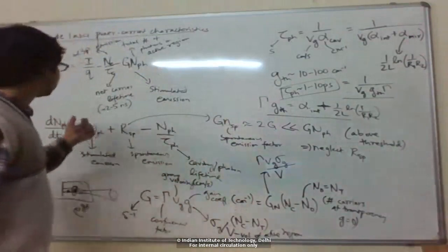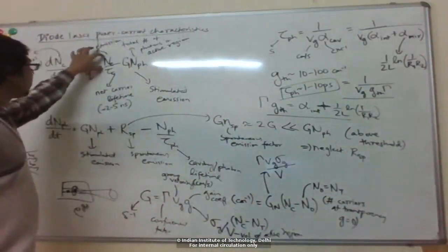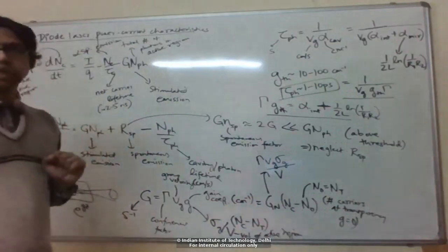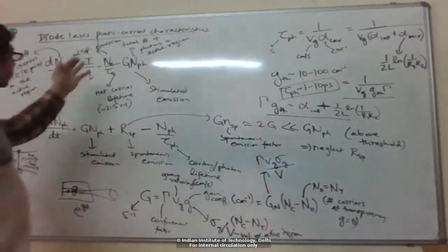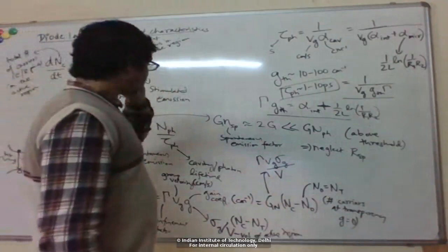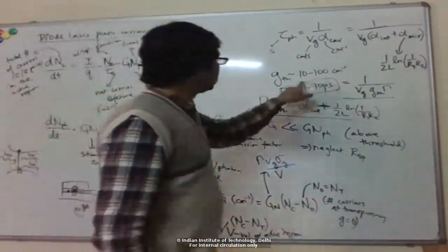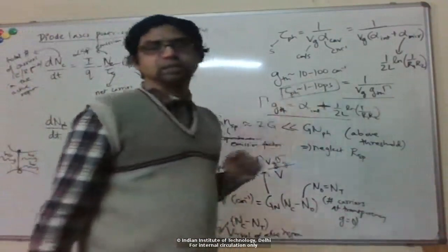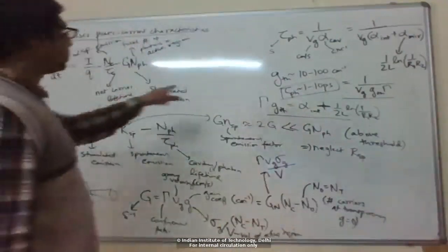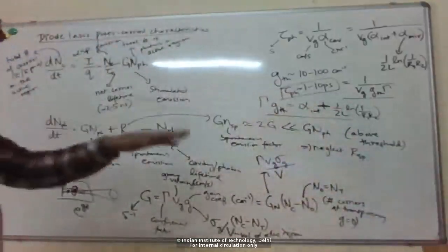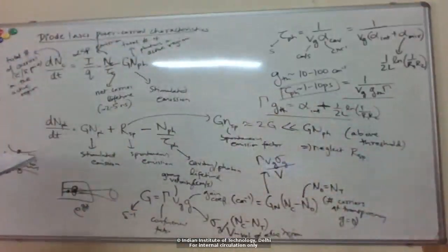With LEDs, the only determining factor was the carrier concentration, which responds quite slowly, nanoseconds. But now in the laser, we have these two dynamical quantities coupled to each other, and one of them is responding much faster. So we'll see that because of this, we can reach much higher modulation frequencies compared to LEDs.